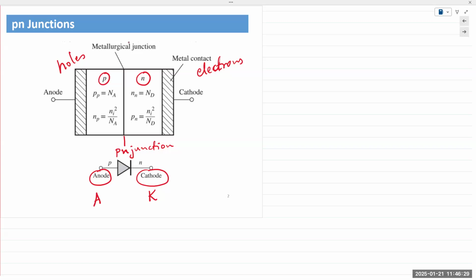Symbol for a diode is an arrowhead with a line at the tip of the arrow. The line signifies that it's the cathode. And on real diodes, this line is typically marked as a band. It's some sort of colored band. The diodes that we use in the lab, the regular silicon diodes, have black epoxy packaging. It's a small cylinder, and there's a silver gray band running at one end of that material. So it's closer to one terminal, and that terminal indicates it's the cathode.